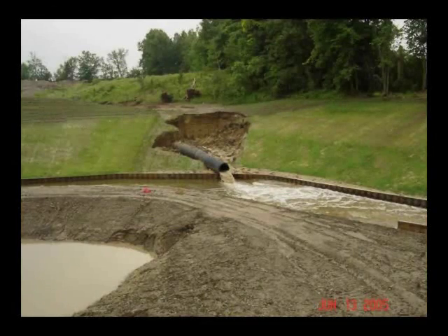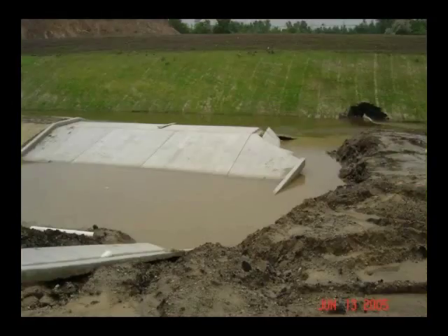Inspectors need to examine the basin outlet and ensure that water leaving the basin is not carrying sediments and that no erosion is occurring at the point of discharge. Sediment discharge and erosion around the outlet are signs that the treatment time needs to be lengthened and the velocity of exiting water needs to be slowed.